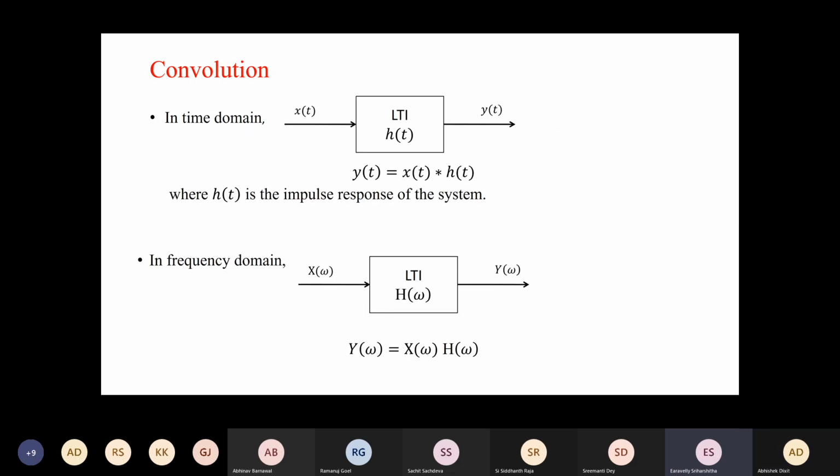Okay, fine. So let us understand this importance. For an LTI system, I already know that y(t) is x(t) convolution with h(t), where h(t) is the impulse response of the system. So in the frequency domain, we can write this equation: Y(omega) is X(omega) multiplied by H(omega). Deriving this, I haven't used any vector knowledge. So similar results can be derived otherwise also.